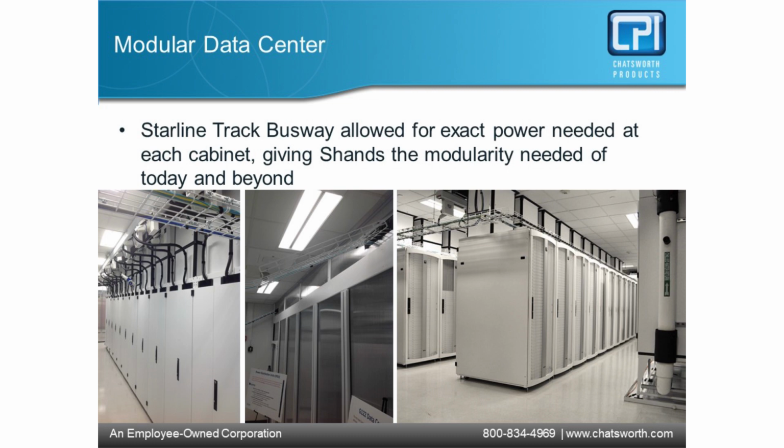So you'll have a run where they'll utilize potentially our 225 or 250 amp product, and then in the high density, the 400 amp product or the 800 amp products deployed. And once again, a myriad of plug-in unit combinations, with 208 scenarios, 120/208 scenarios, or a lot of the larger facilities now are going to the 400 or the 415 volt installation.